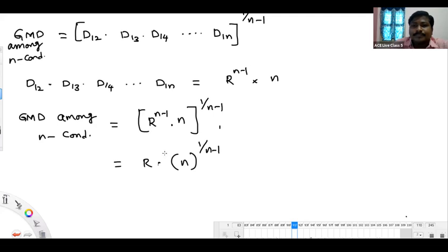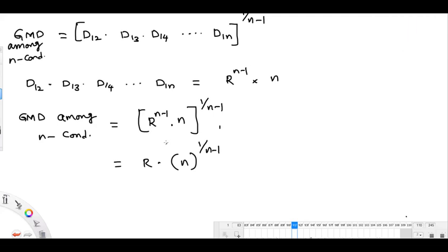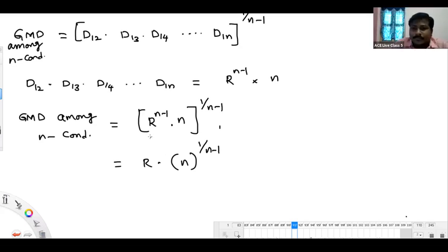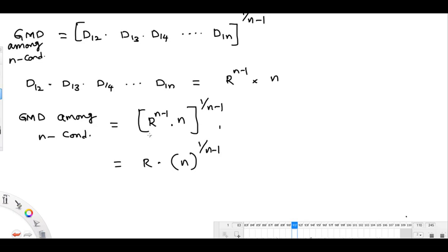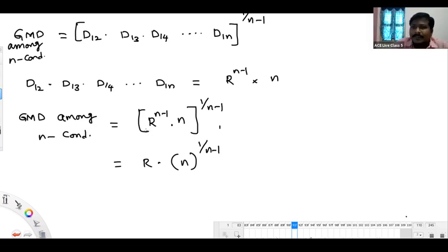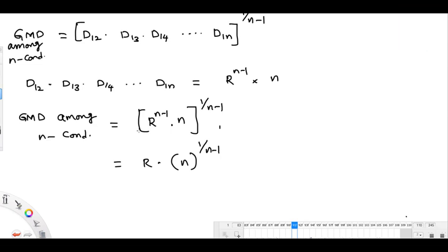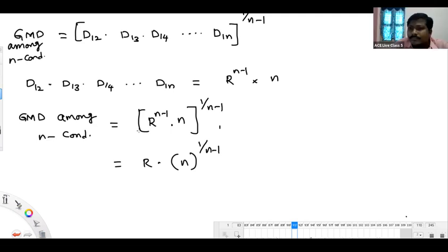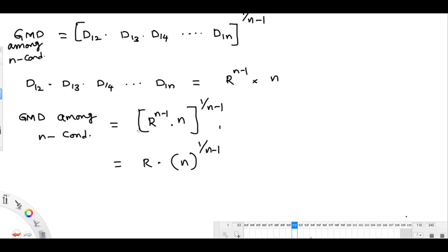Avinash: Sir, you have told about one copper conductor and three aluminum conductors. How to find GMR in that? You have to take some current I, and divide that current between them using their resistivities. The current division formula you have to apply. Sir, will you please explain it in short?